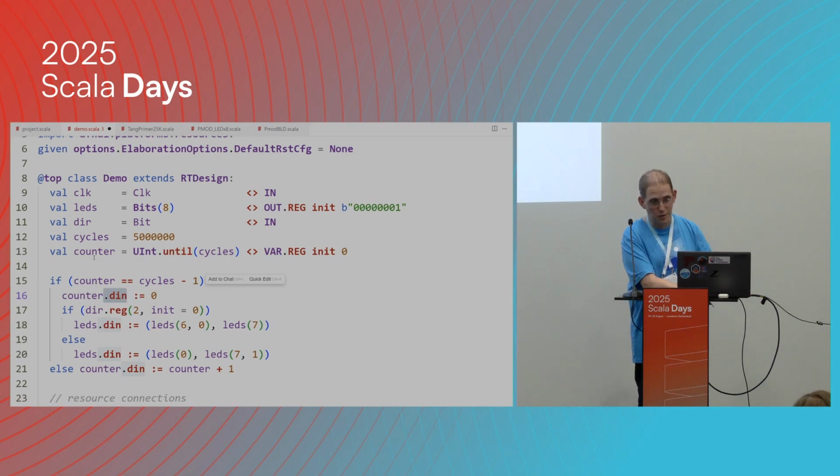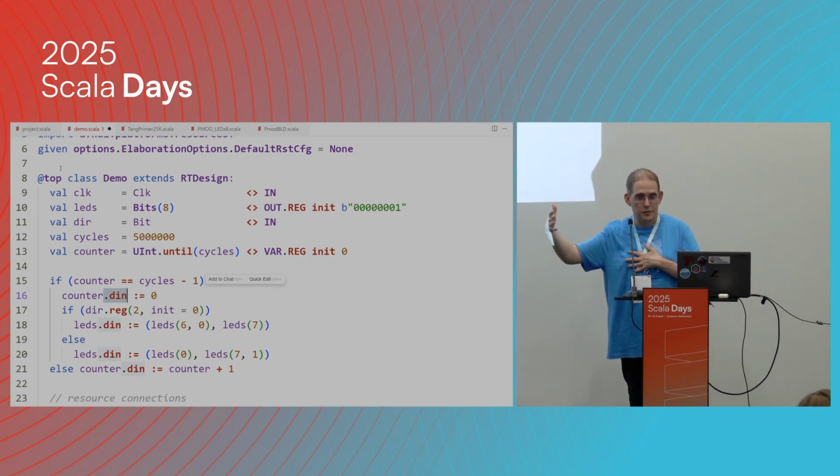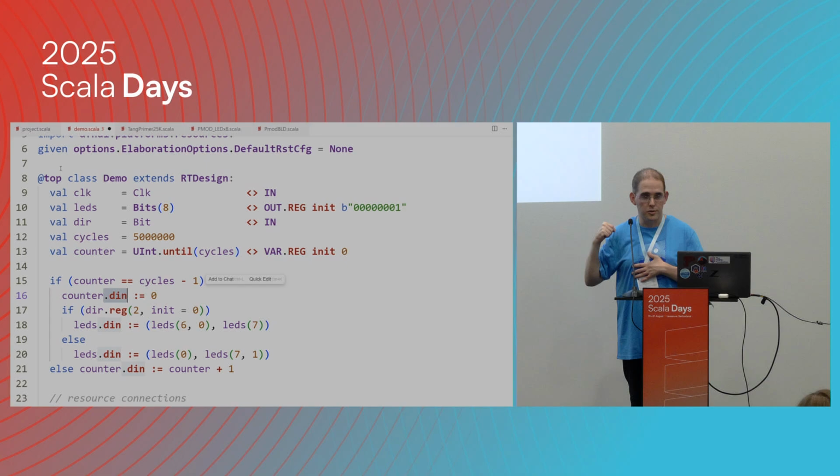But what I most want out of the capabilities, and currently I don't know if it will be capture checking, I don't know if it will be possible, is when we have different designs instantiated one in another, I want to know if a design is truly pure, that it's using only parameters that it doesn't get from anywhere else. And once I do that, then I know that I don't need to reinstantiate that design again and again. I can, at compile time, remove every instantiation of that design except the first, and reuse old cached instantiations. So I can save a lot of runtime during elaboration. But again, I don't know if it will be possible using the separation checking.